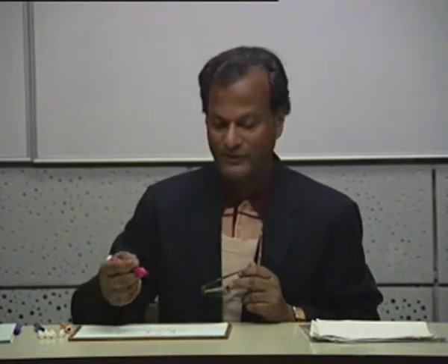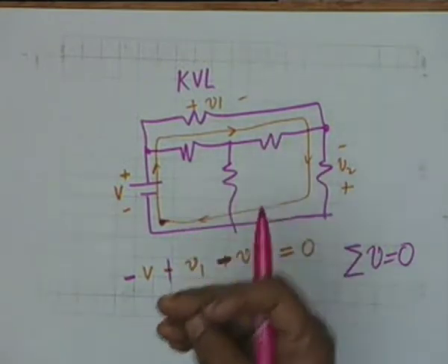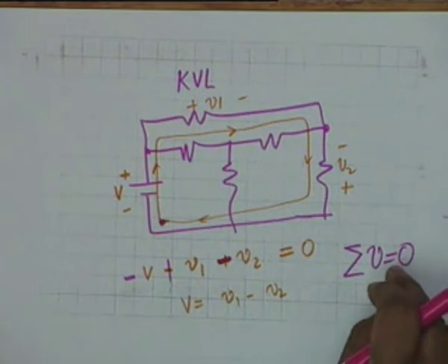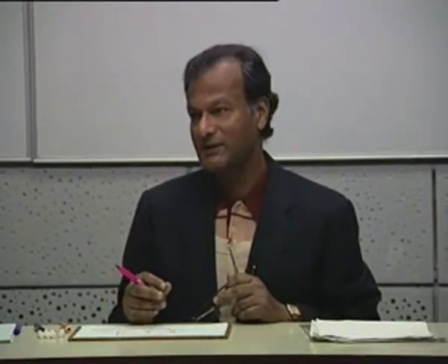And if you take a unit positive charge through a potential difference of V, obviously the work done is V, and if you take it in the direction of potential drop, work done is positive. If you take it in the opposite direction, work done is negative, and that unit positive charge, or any charge Q, cancels out from both sides, and therefore you are left with only voltages or potential differences, and this basically is KVL. Did you know of this interpretation earlier?